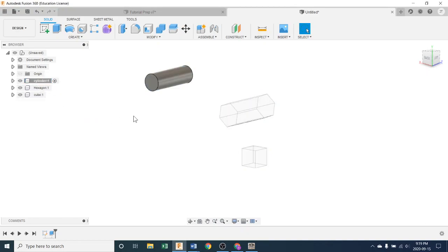So that's components. You have to work with components. You're going to be drawing things with two components, like my lid box or lid bottom of a box thing. That's pretty much all we're going to do for now. But make sure you concentrate on making sure the little radio button is picked when you're trying to draw on either of the components. If you're picked up here, it looks right because everything's on, but your sketches and your bodies won't be associated with the component that they're supposed to be associated with.